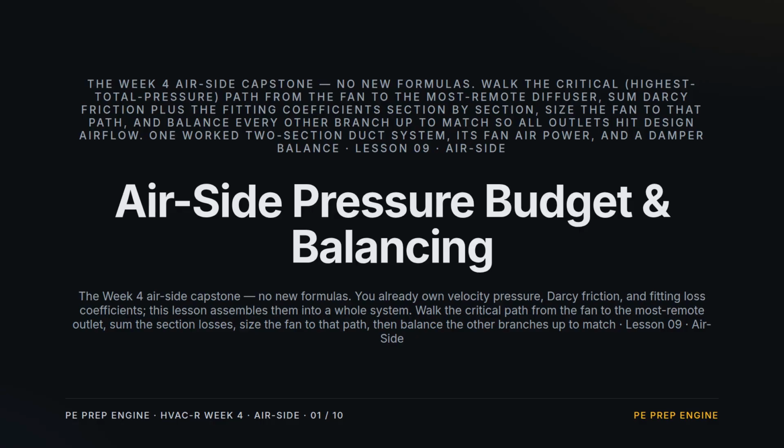Week 4, Lesson 9. The airside capstone, the pressure budget and balancing. No new formulas. You walk the whole duct system end to end, find the path the fan actually has to fight, size the fan to it, and balance every other branch so all the outlets deliver their design airflow.